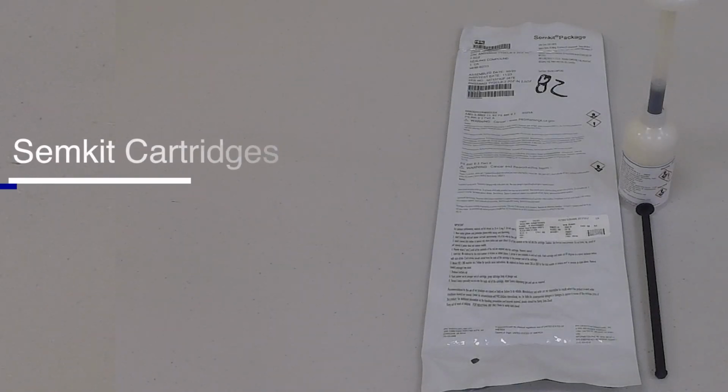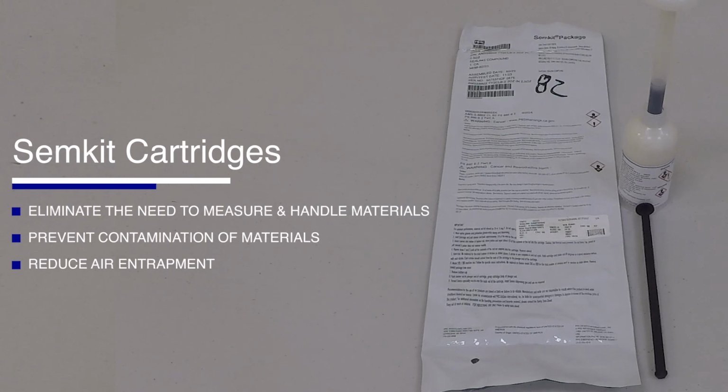Second, the SemKit cartridge is a plastic cartridge assembly containing both parts of the sealant that stores, mixes, and applies sealant materials. SemKit packages are convenient because they eliminate the need to measure and handle materials, prevent contamination when opening and closing 2-part can kits, and reduce air entrapment, which causes voids when mixing sealants.